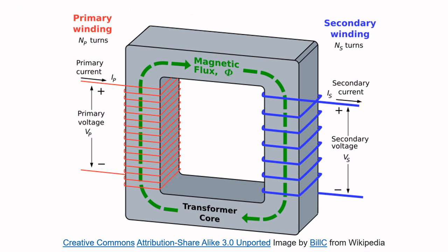Just as the change of current in a coil can induce a voltage in it, the change in current with corresponding change in magnetic flux can induce a voltage in a coupled coil which is very near to it or wound over it. That is known as mutual inductance and forms the basis of transformers. This applies only to alternating current which changes continuously. In case of direct current, change occurs only during the moment the circuit is switched on.